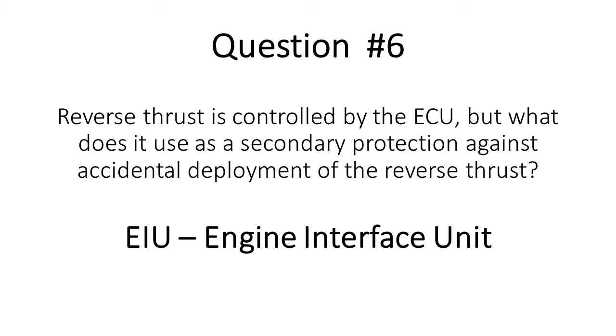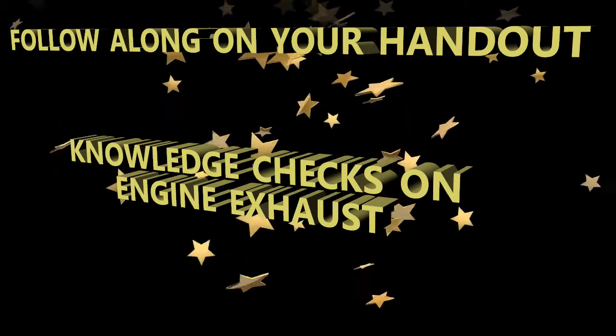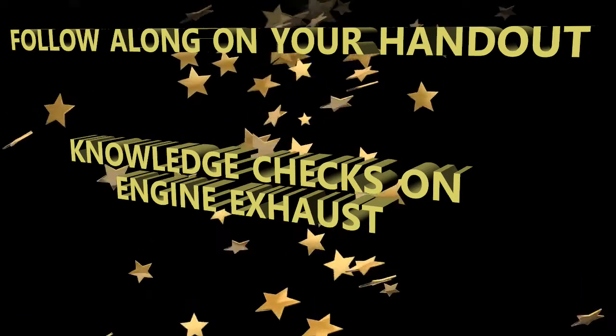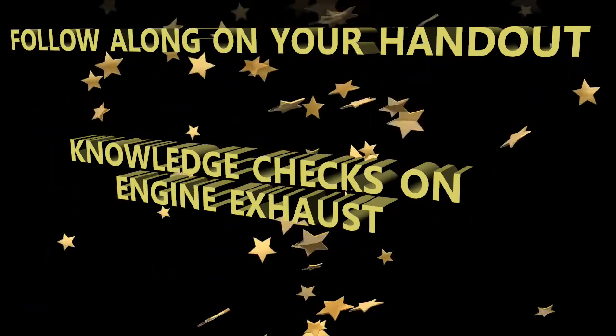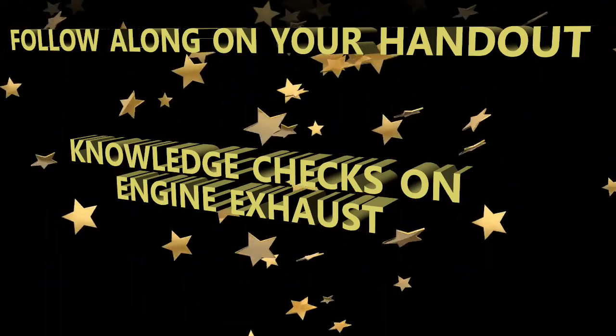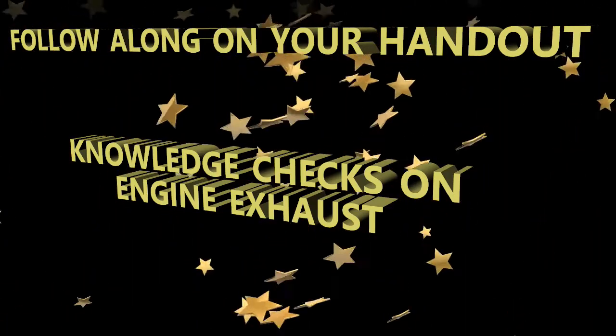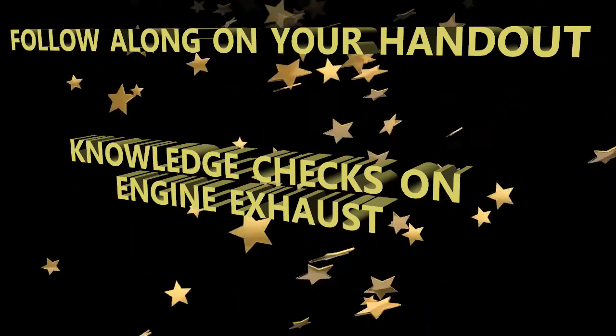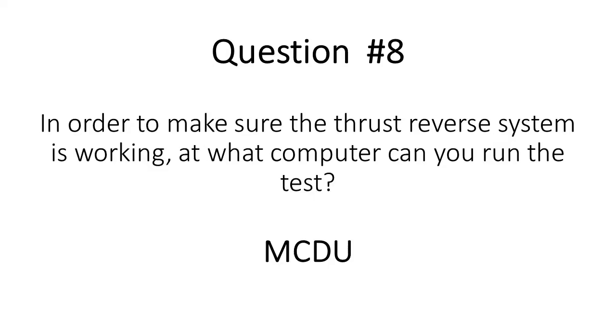All right, I'm on number 7. In order to command thrust reverse operation, the ECU needs the signal of aircraft on ground. Is that true or false? Well, I just said it was true. It has to be getting that information from the landing gear control and interface unit in order to say, okay, yeah, aircraft is definitely on the ground.